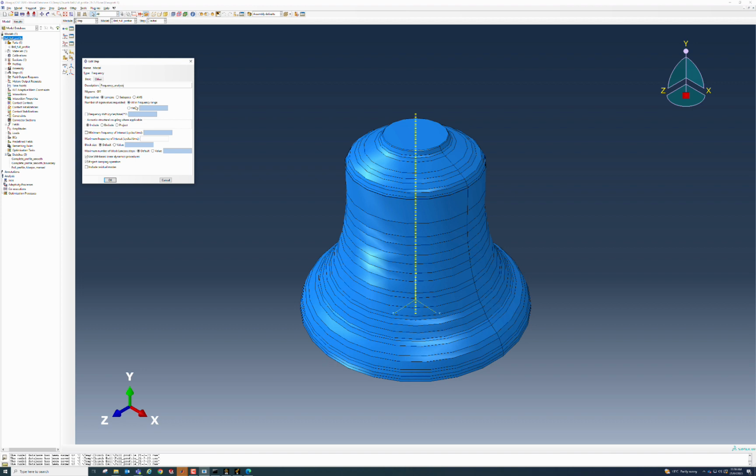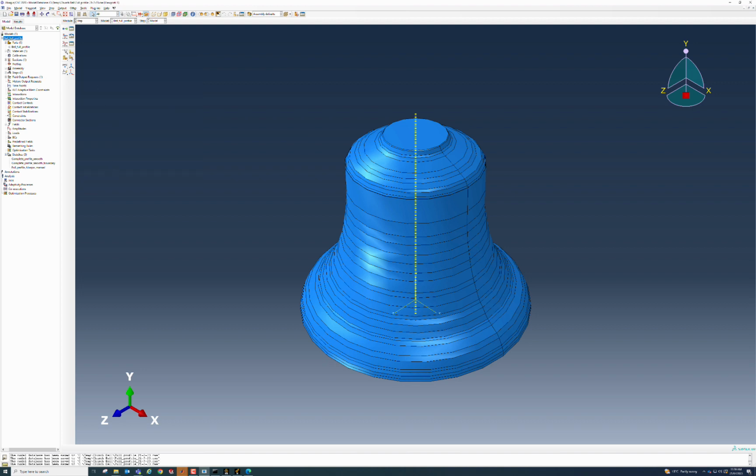We could have multiple steps, for example, within our model file. We could have steps that can be suppressed and resumed depending upon the specific nature of the model. We can also have multiple models within our model database, so once we've built one model, we can copy that model and create different properties that might include having a different step or different loads and boundary conditions and so on. So Abaqus is quite powerful in that respect.